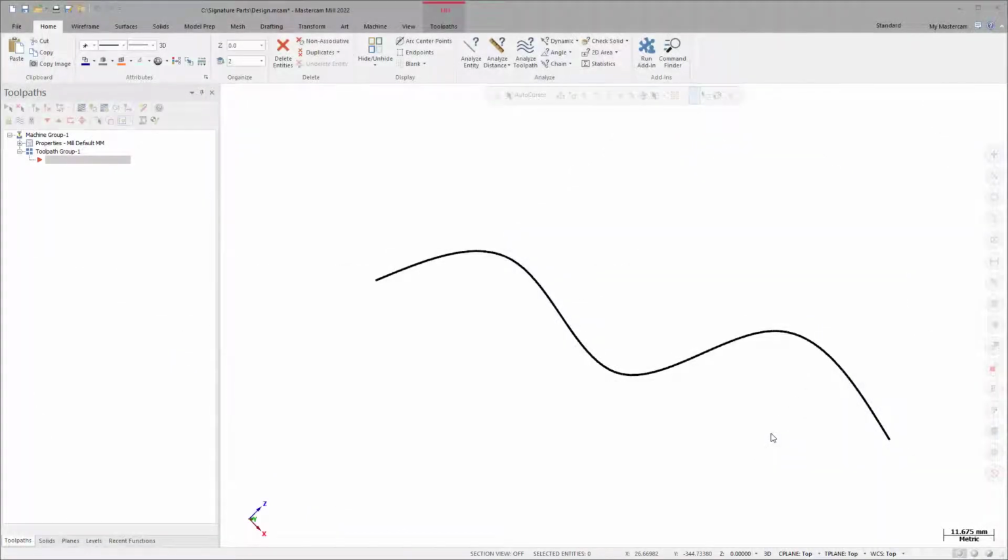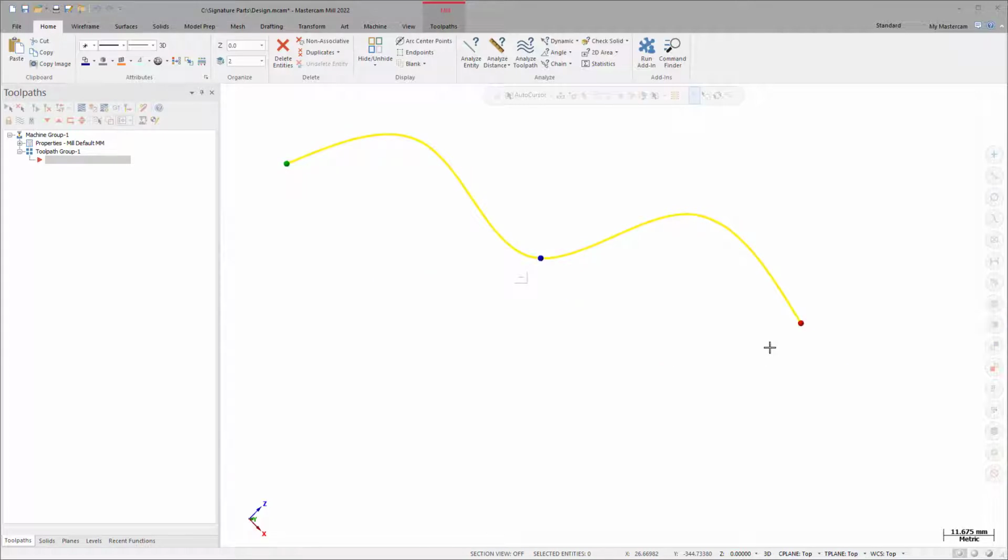Spline controls are the same as the line controls, except that you cannot use top-level editing to change the curvature of a spline. You cannot shorten splines in this mode, but you can increase their length using a linear tangent extension. Use the Edit Spline function to do this. Use the spheres to reposition the spline, maintaining its current length and angle. Hover over the endpoints and select the arrow to extend the length of the spline. It cannot be shortened.